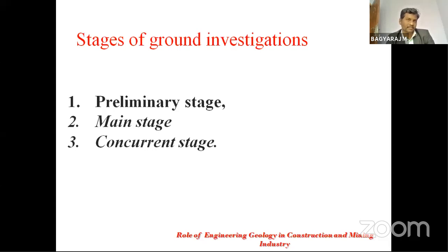For deep investigations, we may go for borehole logging methods and geophysical surveying, as well as collecting a lot of samples for field tests and laboratory tests. Based on these tests, we can make the final reports.